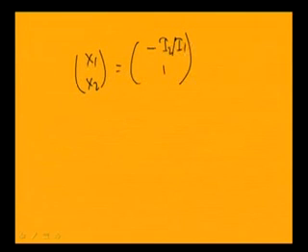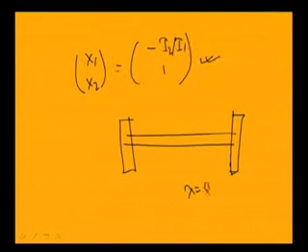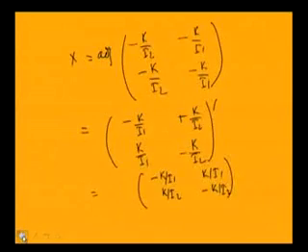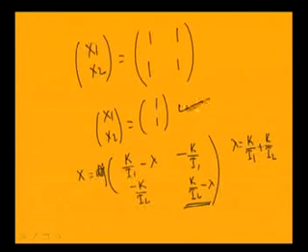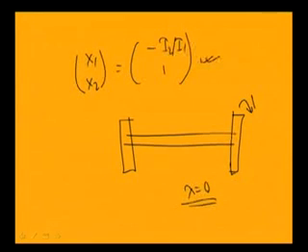So, from this two rotor system you have observed that if you have a two rotor system, in the first mode, that is the rigid body mode, lambda equal to 0. So, you have observed that x1 x2 equal to 1 1. So, in that case both are rotating with the same amplitude. So, when this is rotating with theta equal to 1, this side also rotates with the same theta, that is equal to 1. And in the second mode,